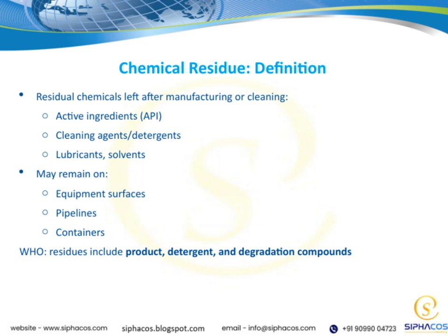It's important to understand that residues are not just the active pharmaceutical ingredients. They can also be byproducts or degradation compounds resulting from the manufacturing process. According to the WHO, residues can encompass the product itself, any detergents used during cleaning, and compounds that form due to degradation. Recognizing and controlling these residues is crucial because they can impact product quality, safety, and compliance. So, this concept of residues ties directly into our overall focus on ensuring pharmaceutical safety and quality at every step.